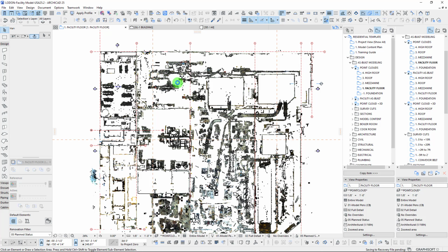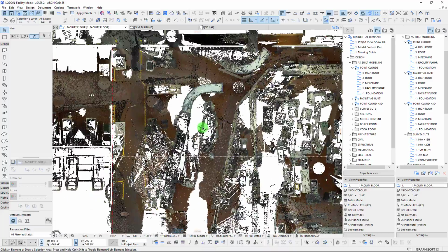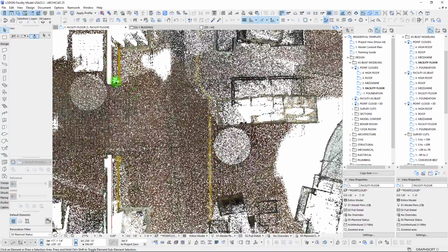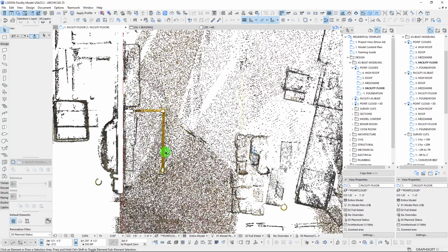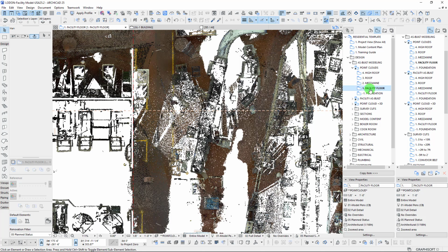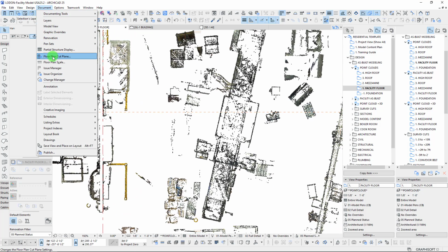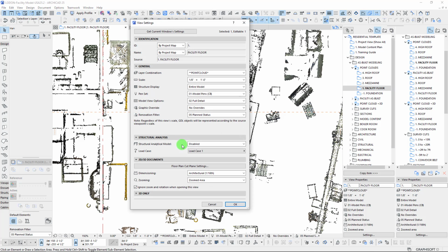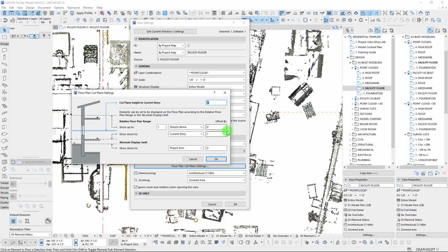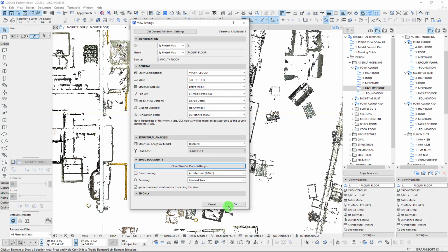You'll see that we're going to start bringing in a lot more of that floor surface here, which really doesn't do us a whole lot of good. Yeah, maybe it's nice to be able to see where some of those painted traffic lines are, but that doesn't really help us out that much. We can click on this again and default that back, because we changed it in our temporary settings here versus going into our view settings and updating our floor plan cut plane from this location. So that's a pretty nice cut right there from 4 to 1.